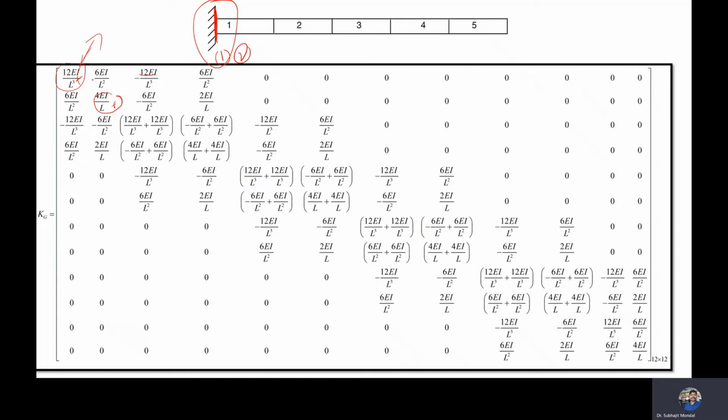If this value 1, 1 and 2, 2 value is sufficiently high in comparison to the other degree of freedom value or other off diagonal term, in that case this stiffness basically will represent your fixed boundary conditions. So if we apply this type of boundary conditions, we can have cantilever like boundary conditions, and we can have the solution. So here we have discussed that K matrix.